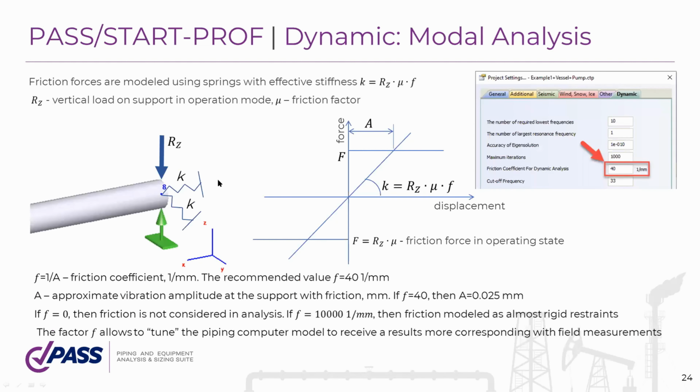Another problem is the friction. Actually, friction forces affect the natural frequencies results very significantly. The results may change several times. How do we deal with that?